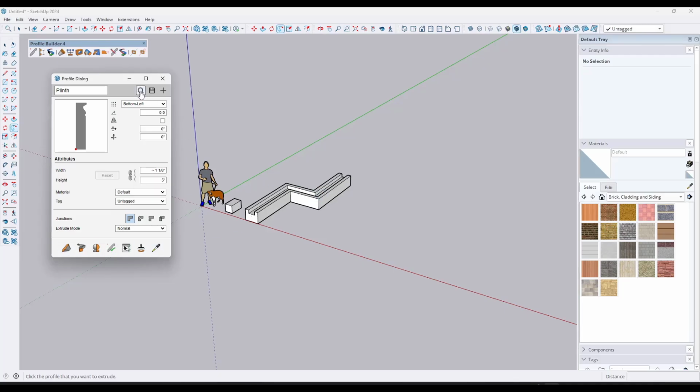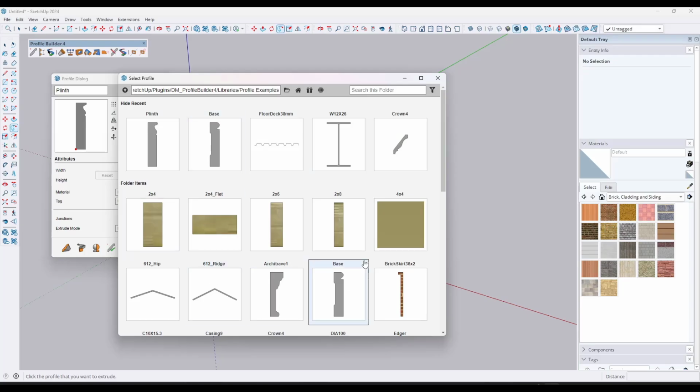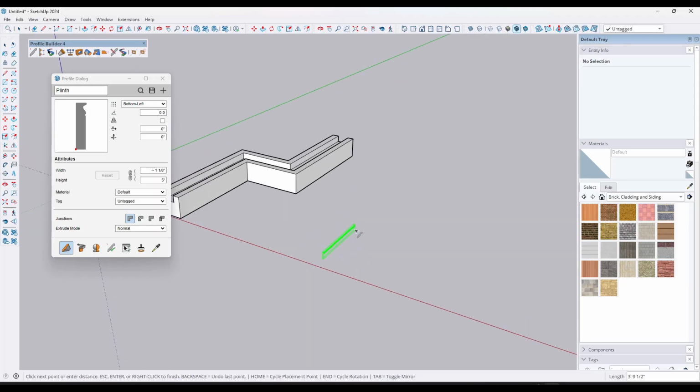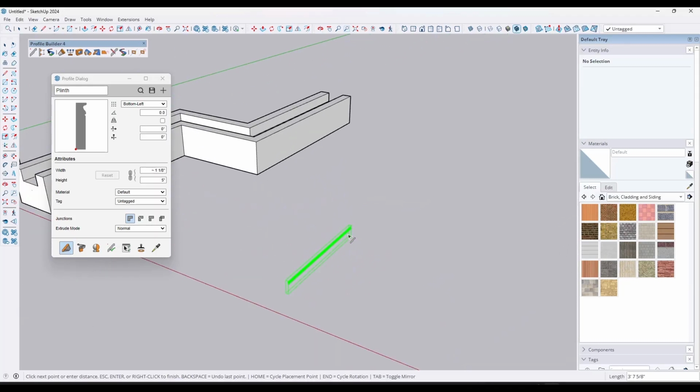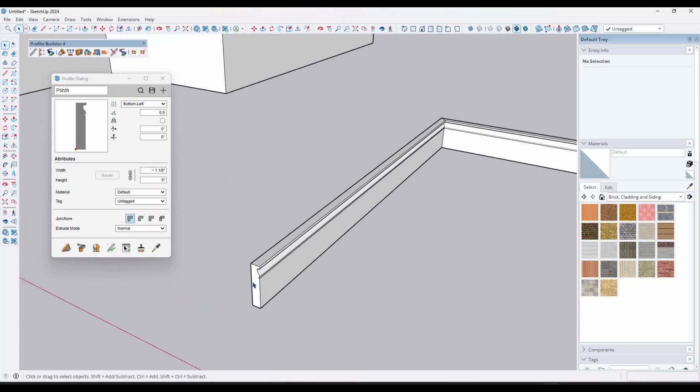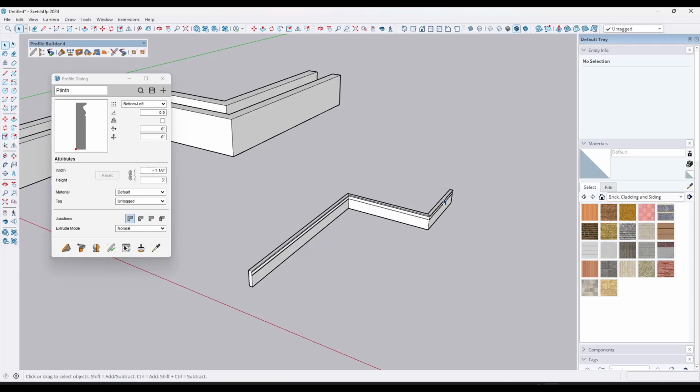And so notice how when you open this up, you can find built-in profiles to kind of practice with. So usually what I would recommend is go ahead and start just by picking one of these profiles right here and just creating a shape. So in this case, if we click on this button right here for build, then what we can do is we can go into our 3D space and we're able to single click. And what this is going to do is it's going to take that profile and it's going to extrude it to 3D like this. So very similar to drawing the profile in here and then using the push-pull or the Follow Me tool. However, this is a lot more powerful for a lot of different reasons.